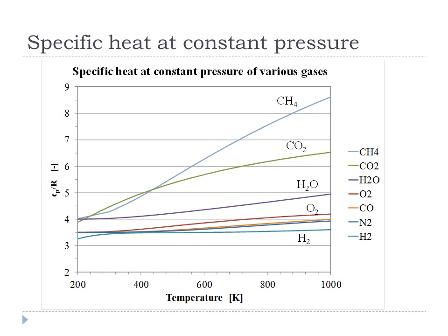So let's go back to this graph here and see what's happening. Let's first look at the hydrogen. Hydrogen hasn't yet hit 3.5 on the C sub P. That's because at 200 K, it still is not completely rotationally active. It's not until you get to about 300 Kelvin that it's completely rotationally active. And then it stays fairly constant between 300 Kelvin and 1000 Kelvin.